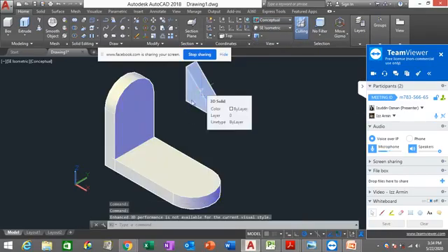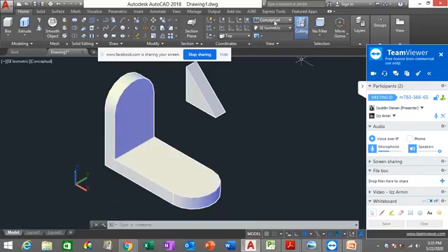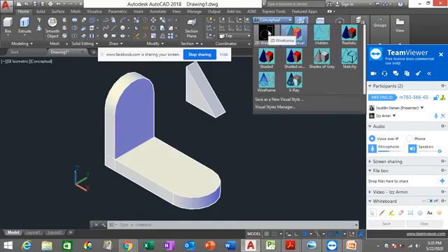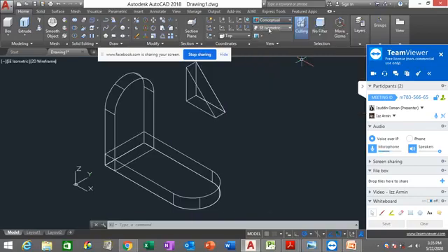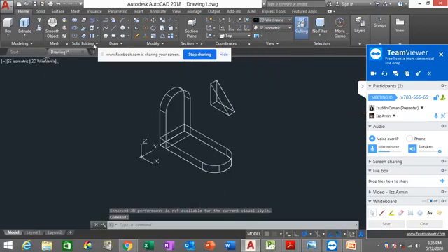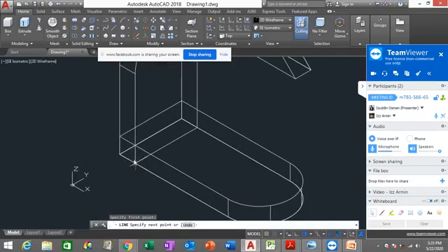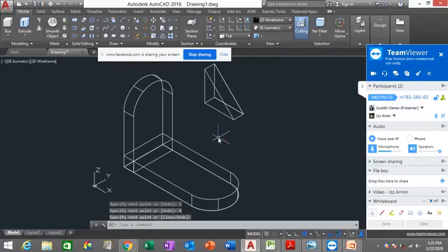Okay, so now what you want to do is move this triangle on top of these two object surfaces. So you need to create a reference line. So you have to go to 2D wireframe first, and click line, go here, polar track this one, 1 enter, 4 enter. So I'm going to demonstrate this first, and after this, if you have any question, you can ask